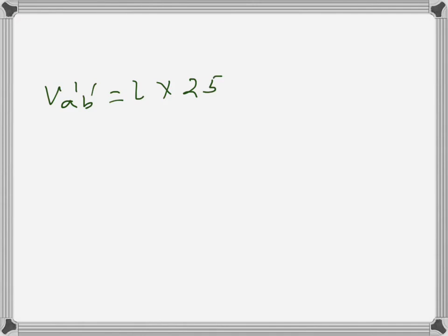There I wrote it like that because I kept the current in milliamps, since I was multiplying by kilo ohms and you knew it would work. But when you are designing a circuit, you should always remember that it should actually be in amps. Basically I should have converted this into amps in the previous one also and then multiplied by 25,000, converting to ohms, but I was lazy anyway.